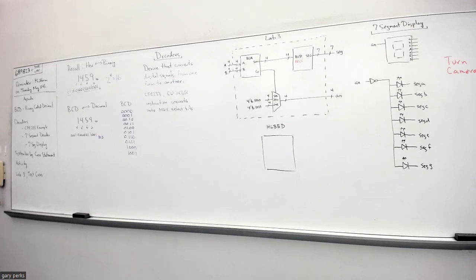If you look at the right side, you have outputs ALU fun, ALU source A, ALU source B, PC source, RF WR SEL. So there are these 5 outputs. If you look in other parts of the diagram, you'll see that those 5 outputs of the control unit decoder go to the select inputs of muxes.